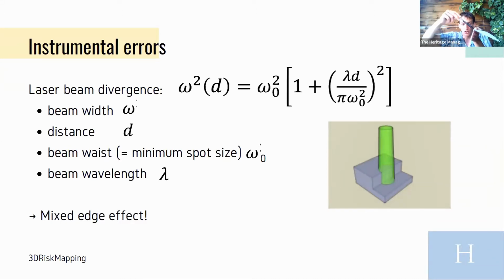So I have my coordinates of that object, but with the laser scanner, it will just measure, measure, measure, measure, measure. And even if you are lucky and the beam spot will just get here, you will actually measure this position here, or this position here, or this position here. And especially on these edge surfaces, you'll end up with a certain amount of mixed pixel effect. So what will you actually measure?